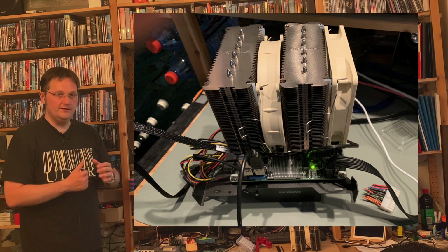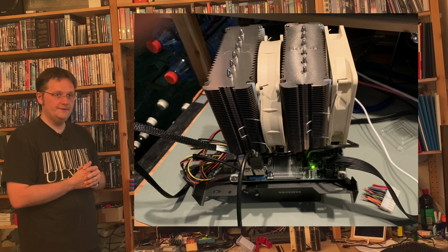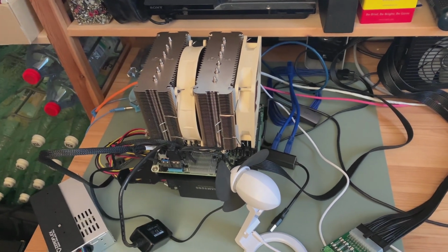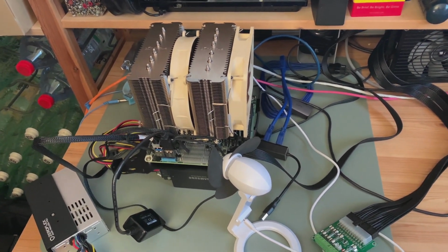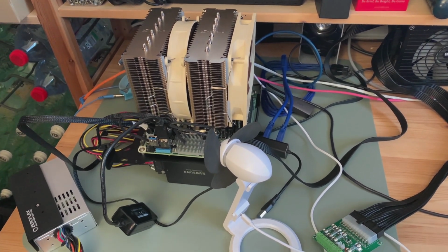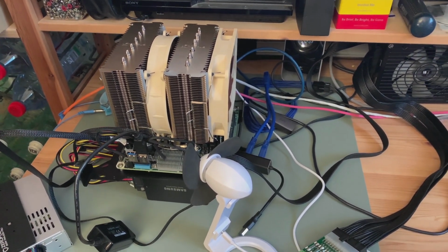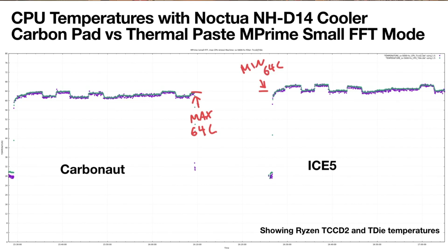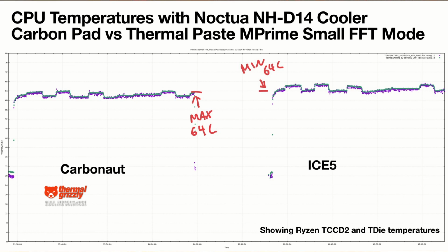As a final part of the thermal analysis, let's look at the CPU. So the cooler that is used here is the Noctua NH-D14. This is obviously complete overkill for that CPU. But for a reference measurement, it was important that we have a cooling solution which will definitely not be the bottleneck. So here I was running Prime95 in small FFT mode, so only inside the CPU, not any other components outside, so we are running completely in cache.